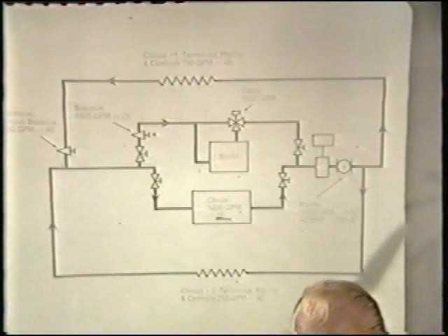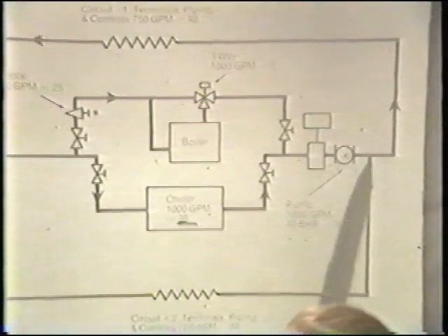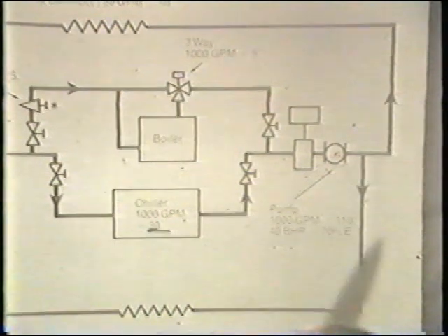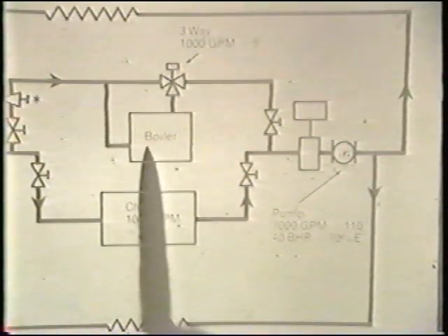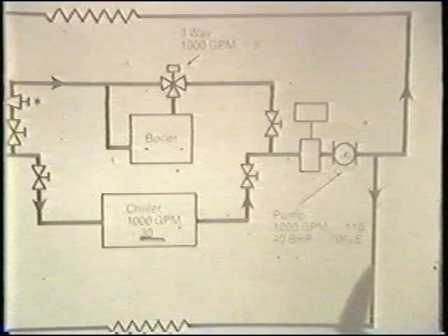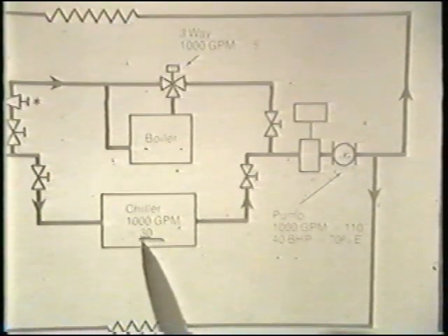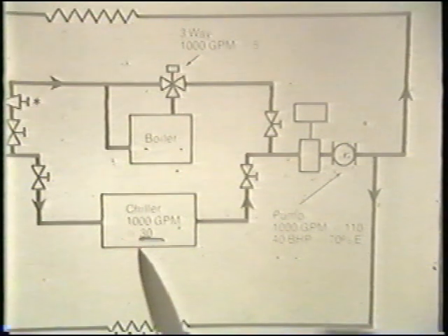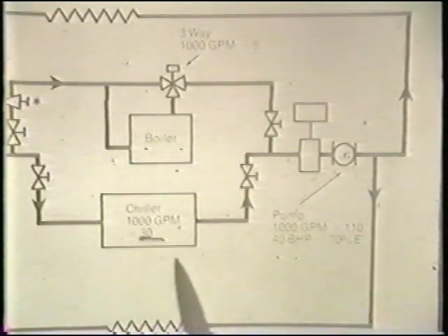But the point is this, that the single pump being employed for this system must, during the wintertime, when needs in terms of head loss through the boiler and its resetting control valve is low, provide and work with the head need of the chiller, even though the chiller is not in operation and valved off.